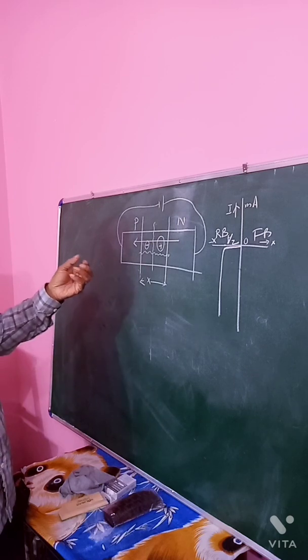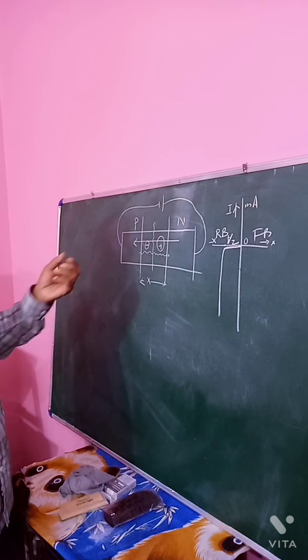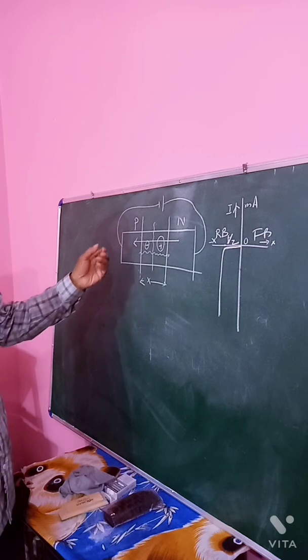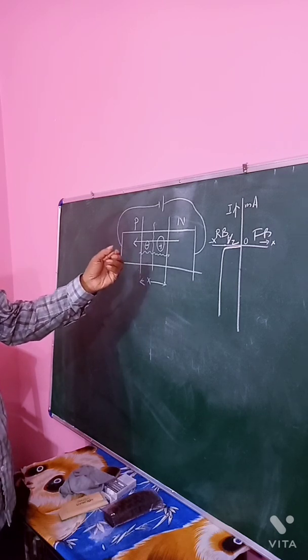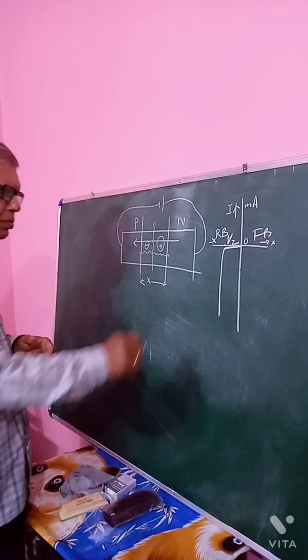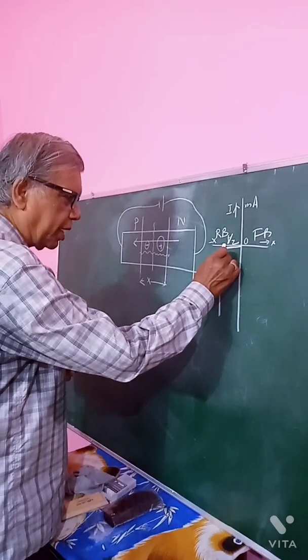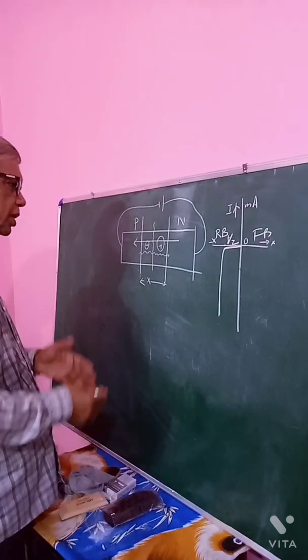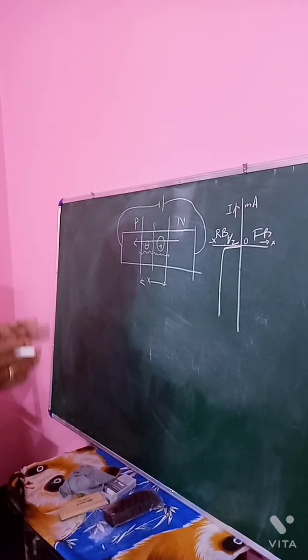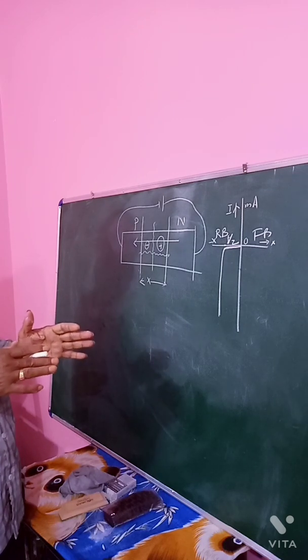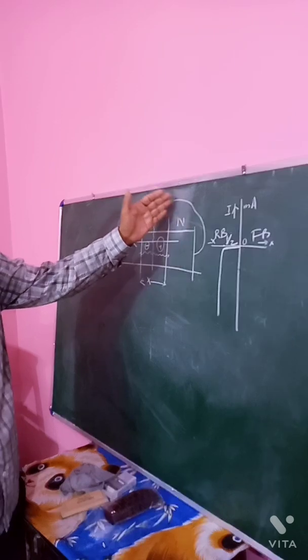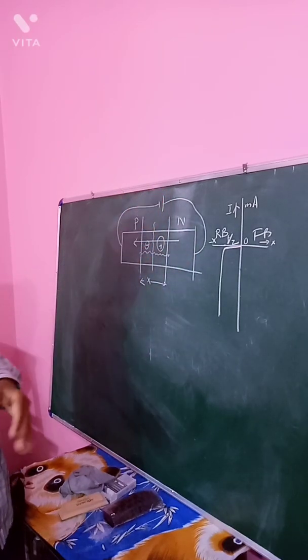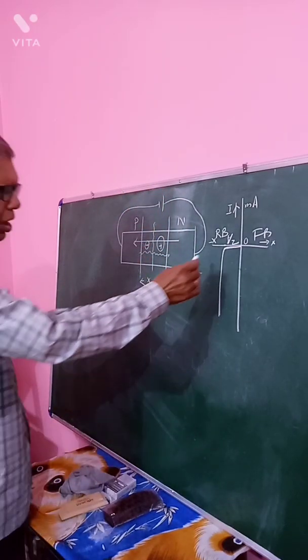As you go on increasing potential, the current varies by a very small amount, but when the potential reaches the breakdown voltage, the current increases very sharply. A very large current flows through the junction, and the electrons are swept out by the positive terminal of the battery. Now why does this occur?